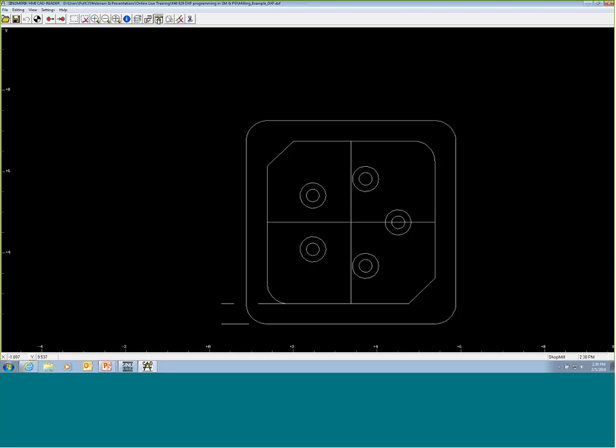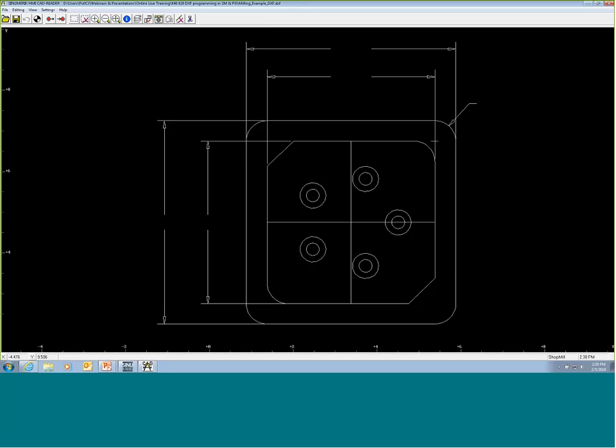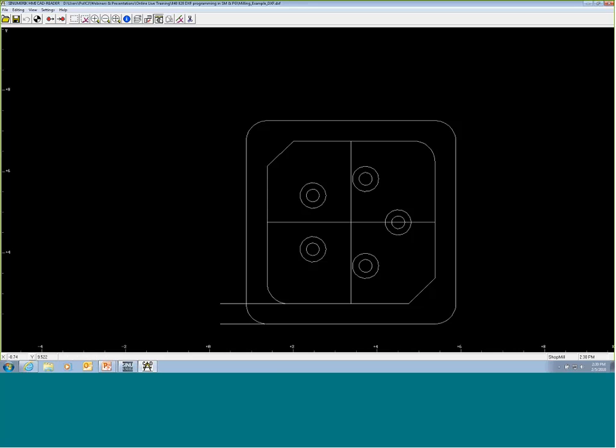But not at any point does this actually edit the DXF file. So you don't have to be afraid. We have a feature here, this one right here, that allows me to delete geometry. If I pick this, I can start clicking on features. Our initial instinct would be, I just deleted features that I need, and now I've ruined the DXF file. Well, at no point does this actually delete these features. If I were to reopen the drawing file, because you're never saving the drawing file, it'll go back to the exact state it was in when I got started. So this is just suppressing or hiding what we're viewing.